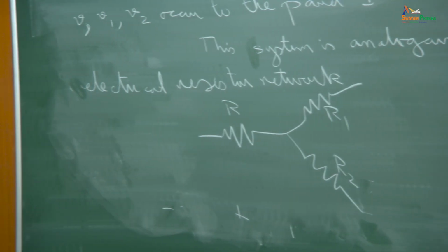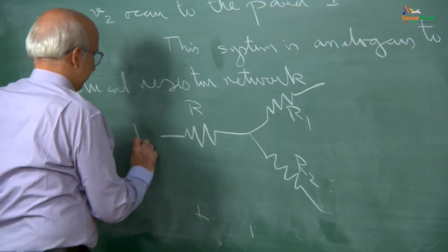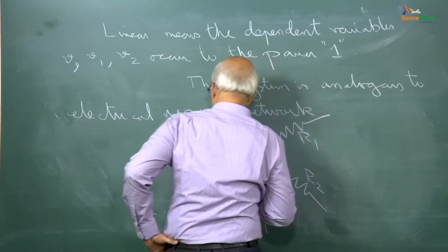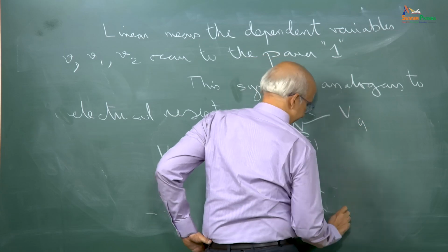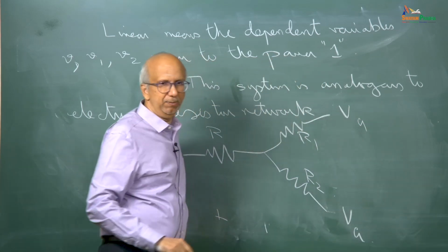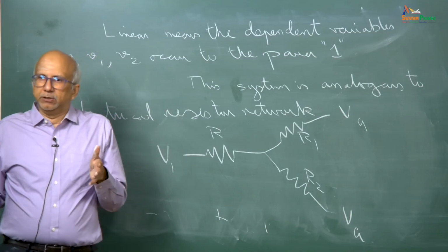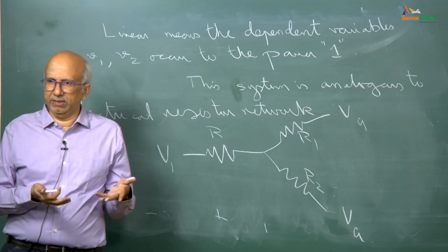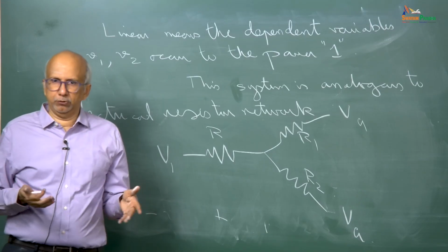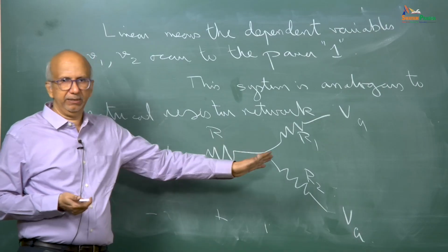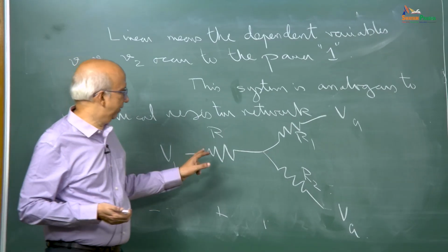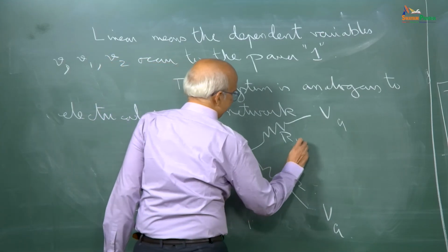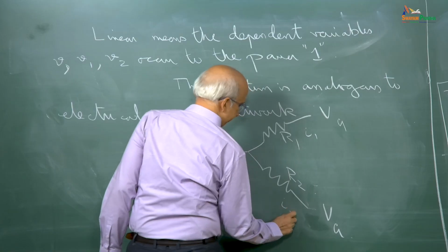Okay. And what we do here is we are assuming the voltages are fixed. Let us say V1, V1 and then this is VA and this is VA, just to keep things similar to what we did earlier. The analog of pressure is voltage. Voltage is driving the current, pressure is driving the flow. So, I am specifying the voltage here, I am getting the current. Objective is to get the current distribution. Okay. So, the current is I here, current is I1 here and current is I2 here.